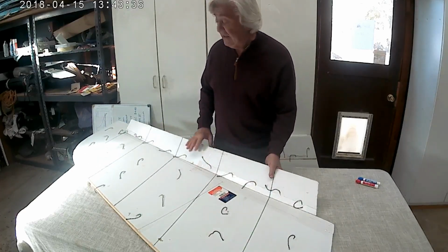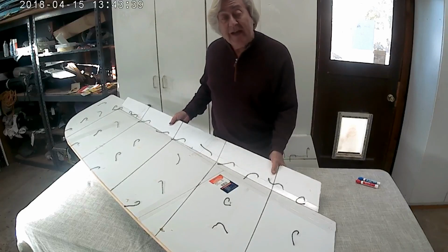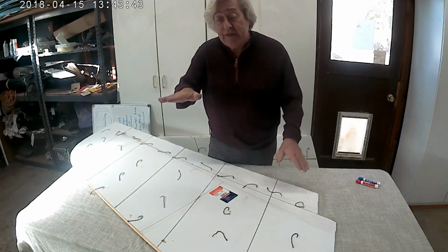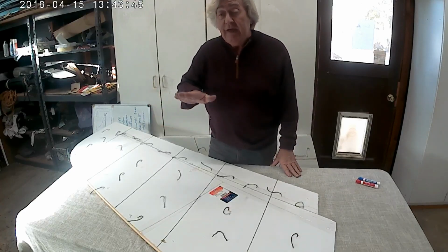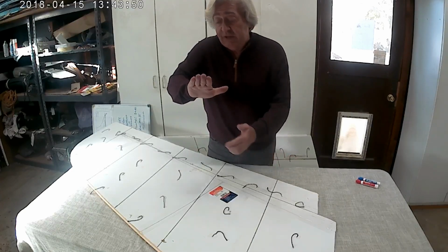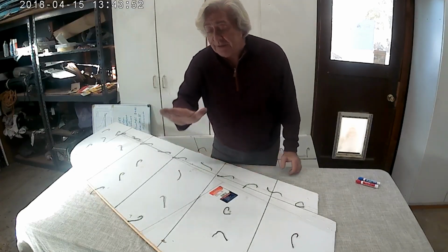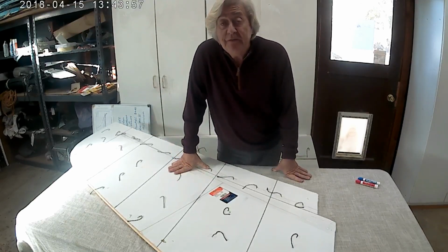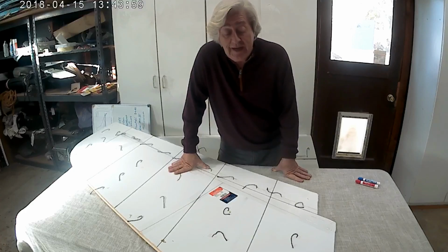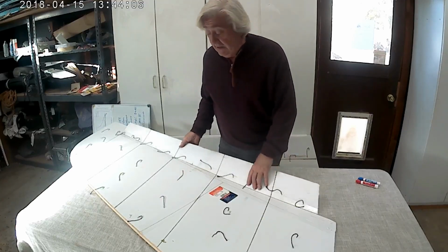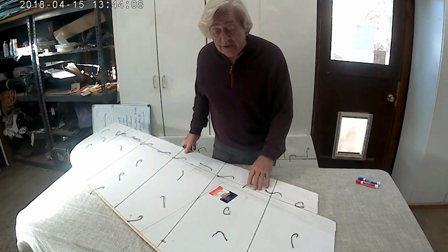When you have this type of elevon on just about any flying wing, as you're in a slow turn like this, if you tweak that elevator up just a little bit too much, it's amazing how fast they break into a spin. It's almost like the inboard wing just stops, drops, goes backwards, and down you go. I've never had to ride through that, but I've had it happen on a lot of models. It's pretty scary. It's bad. So this type of elevon shape causes all kinds of problems.